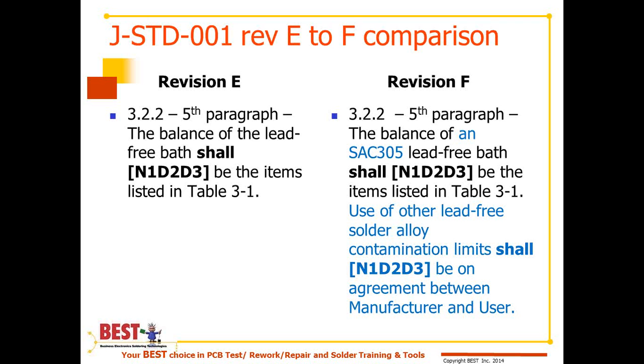Under 3.2, for the fifth paragraph in 3.2, it says the balance of an SAC 305, where previously it just said lead-free bath. Now they've stipulated that SAC 305, lead-free bath, shall be of the items listed in Table 3-1.